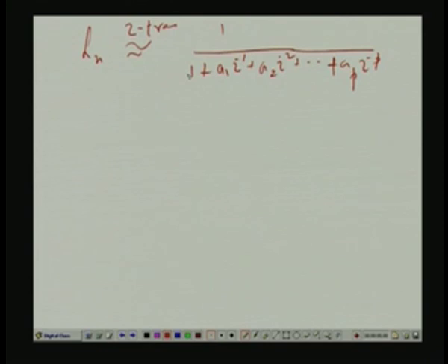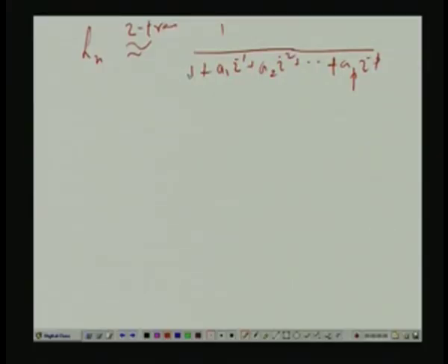Okay, this is basic DSP. For a causal transfer function H z, if you let z tend to infinity, what happens? What is H z? Summation H n z to the power minus n, n starts at 0, goes up to infinity. So, H0 plus H1 z inverse plus H2 z inverse 2 plus dot dot dot. Here, if you allow z to go to infinity, all terms disappear except for the first term, which is H0. So, what you get is H0. So, in this expression, if you let z tend to infinity, all this A1 z inverse, A2 z inverse 2 and all that disappear, only 1 by 1 results, and it is 1 because H0 was 1, as we saw last in the previous slide, in the previous page.